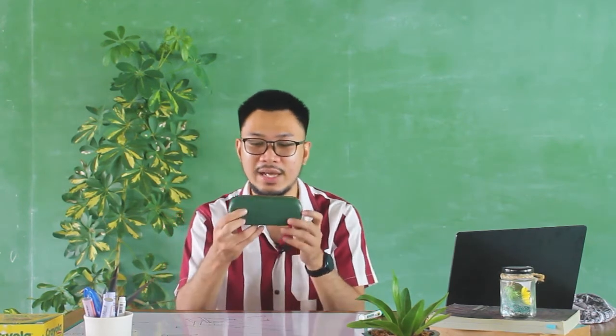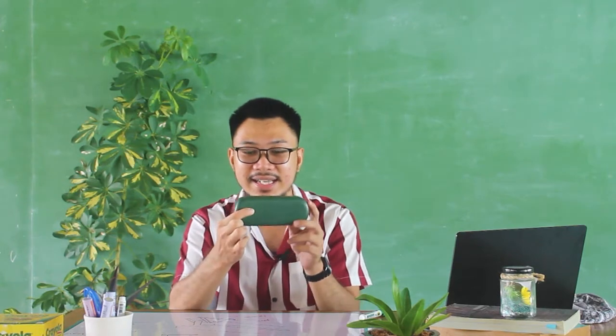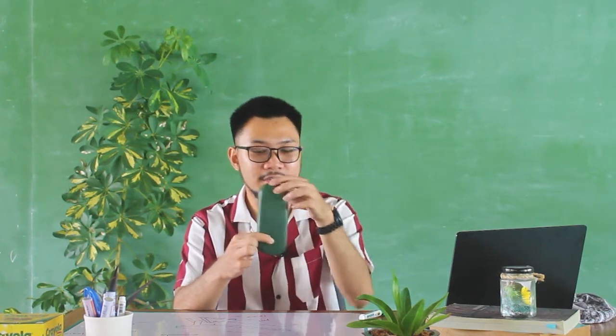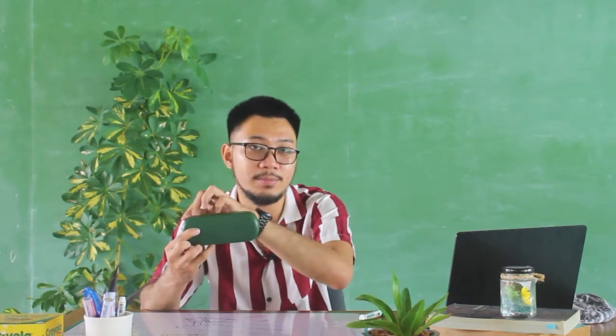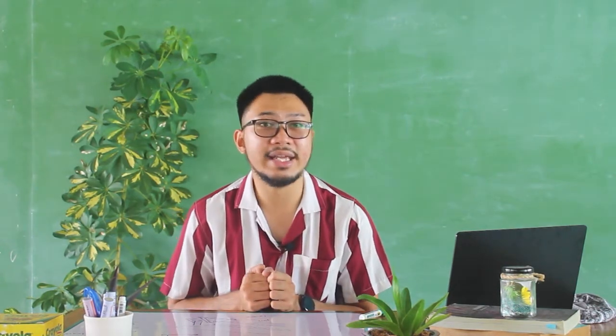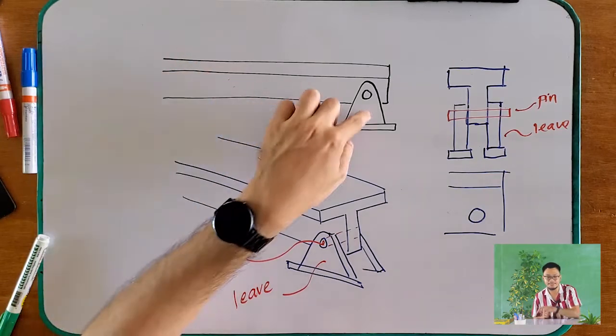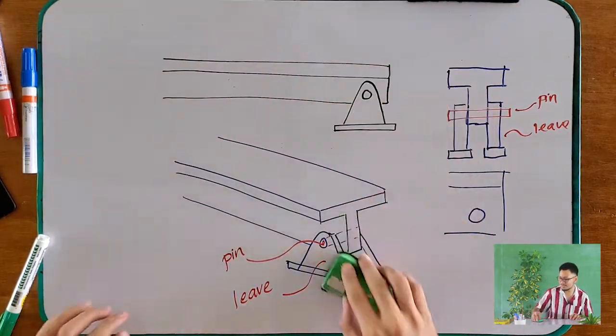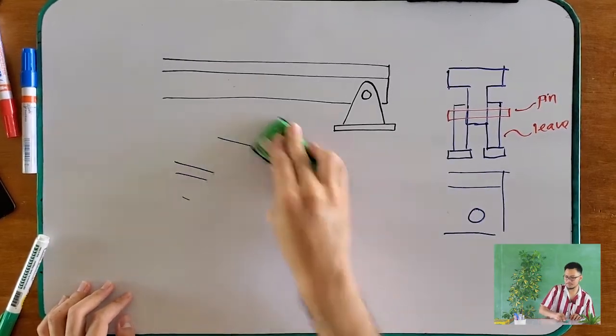Pero, unsa may inyong nabantayan? How about if you are going to create a rotation out of this beam? Well, since pin man siya and then loose man na siya, then it can freely rotate. So, this one does not support your moment, but it only restricts the forces along the x and y components. But again, it can rotate your beam. It enables your beam to rotate. Okay? So therefore, if you are going to create a free body diagram of this beam with this pin support, then this is what you are going to draw.